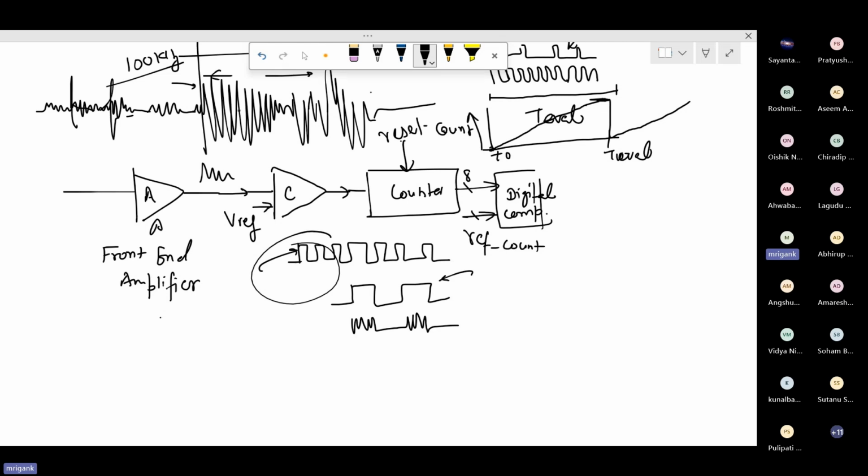Now, if the frequency content is up to 100 kilohertz, then we can target that. Within 1 millisecond, how many pulses are you going to get? 100. So within maybe 100 milliseconds, you will get a large number of pulses. Based on the observance of the data, we can decide to target, say, a 100 millisecond detection period. So T eval equals 100 milliseconds at max, 0.1 second. If you are able to detect within 0.1 second, then definitely the further effects can be suppressed. This is a very good detection period.